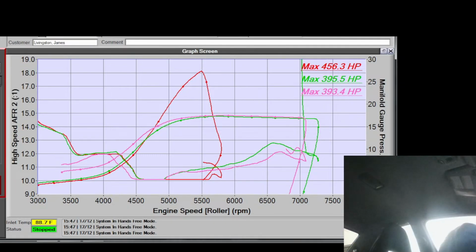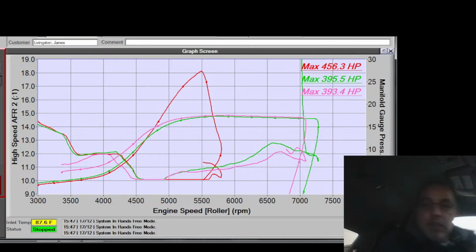Okay, Will Morgan says inertia for current. Okay, and the other one's inertia for voltage. That's an interesting way of thinking about it. I don't know if I like the term inertia in that regard, but I see what you're saying. Yeah, so current, right? So an inductor would resist change in current, right? And that's either direction. And so I guess with inertia, you're saying something in motion tends to stay in motion, or something at rest tends to stay at rest.